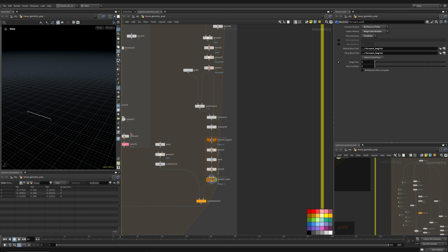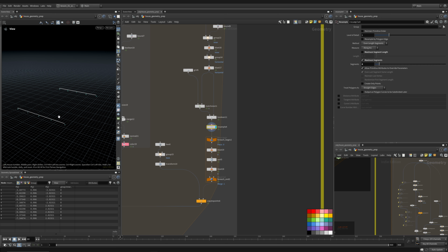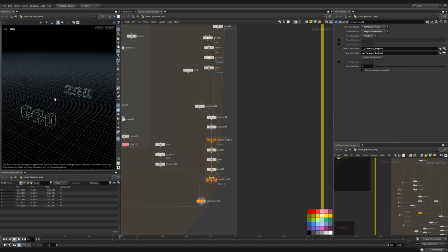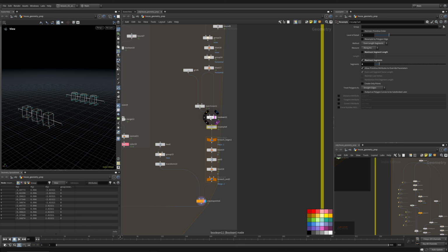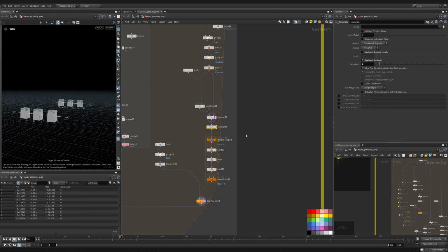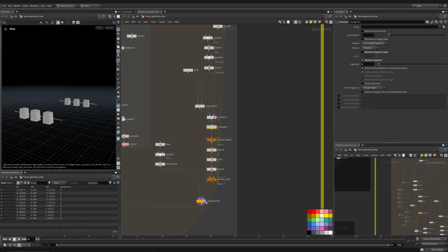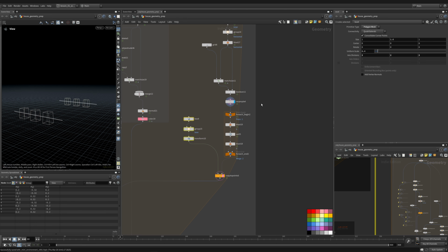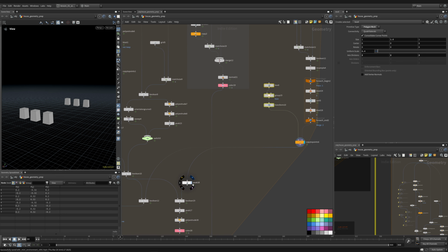So that let me remove the points while keeping this procedural. I'll show you, I'm going to disable this. I could technically have as many of these points as I want, but I will never have them on the outside here. If I click resample, more windows are being added, but they're never on the outside, which is what I wanted. And again, there's definitely lots of ways to do this. This is the way I chose to do it, but I do encourage you to maybe figure out a way to do it with VEX or with VOPs. So lots of ways to do lots of things, which is, again, the coolest part about Houdini.